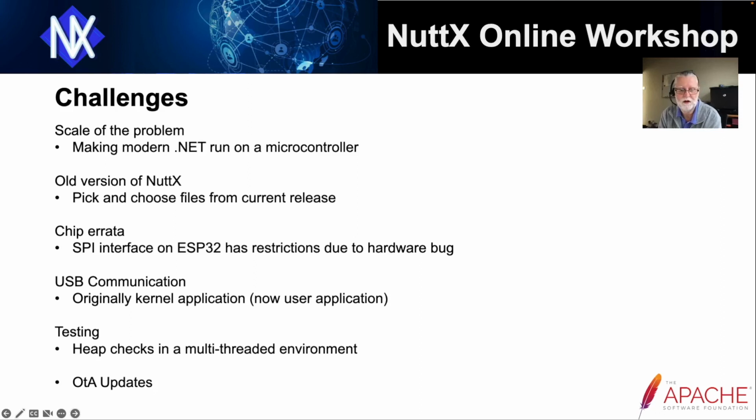So we would fire off a request to the ESP32 for it to pull back a web page, and because of the nature of the system, the memory for the messages that are transmitted between the two chips might be released slightly after we return to the test code, which makes things a little bit interesting when you're trying to compare the heap before a request to the heap afterwards to make sure that you're not leaking memory.